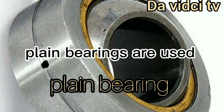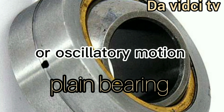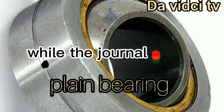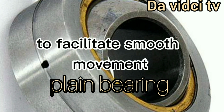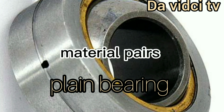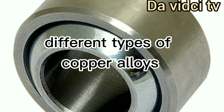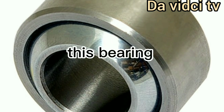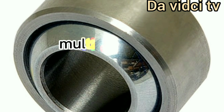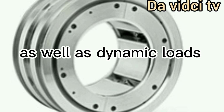Plain bearings are used for rotational, sliding, reciprocating, or oscillatory motion. The bearing remains fixed while the journal slides on the bearing's inner surface. To facilitate smooth movement, material pairs with low coefficients of friction are selected. Different types of copper alloys, for example, are pretty common. This bearing can accommodate some misalignment, multi-directional movements, and is suitable for static as well as dynamic loads.